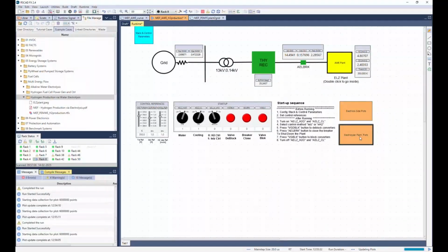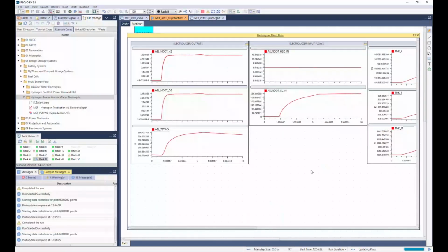In this hierarchy box, you can see all the plant waveform related to the hydrogen energy side. First, you can see the plant hydrogen and oxygen production rate in these two waveforms. Then you can see the stack temperature dynamics. Due to the start of the reaction, temperature is slightly increased but starting to come down. Typically, this stack temperature has large time constant, therefore it takes long time to settle in steady state.